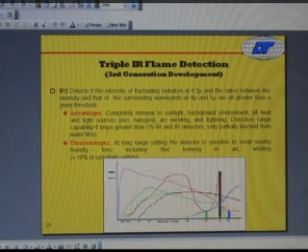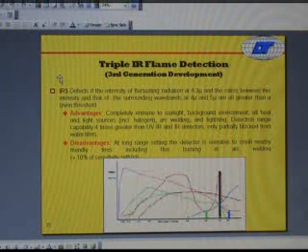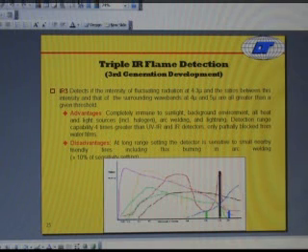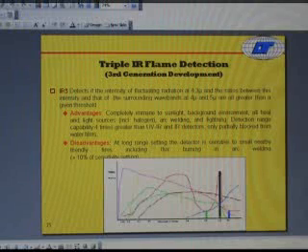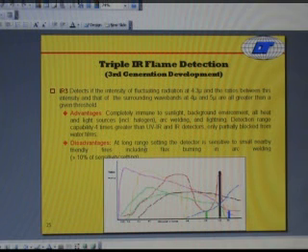Detection range is 4 times greater than UV-IR. That's why we use this one. It's very sensitive, and we use it everywhere in our modules. Disadvantages: long range setting, and the detector is sensitive to small nearby friendly fire, including flux burning and arc welding.